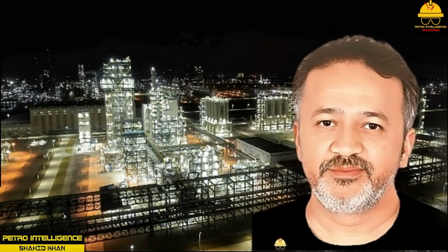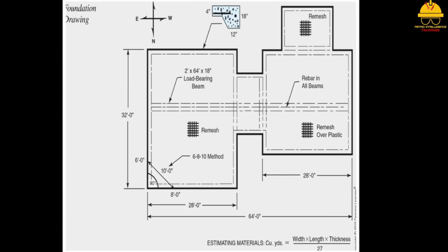Foundation drawing. The construction crew pouring the footers, beams, and foundation uses foundation drawings shown in this picture. Concrete and steel specifications are designed to support equipment, integrate underground piping, and provide support for exterior and interior walls. Process technicians do not typically use foundation drawings, but these drawings are useful when questions arise about piping that disappears under the ground and when new equipment is being added.